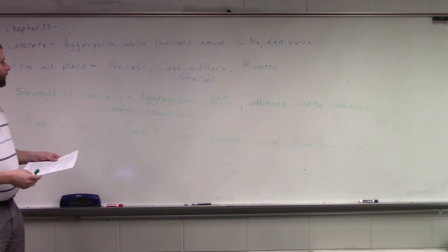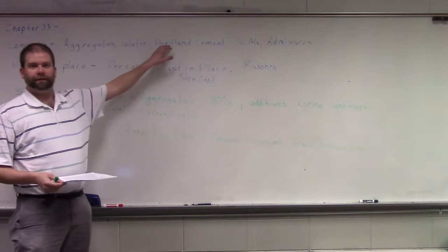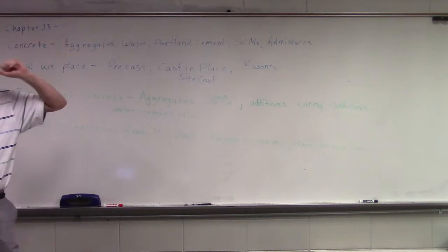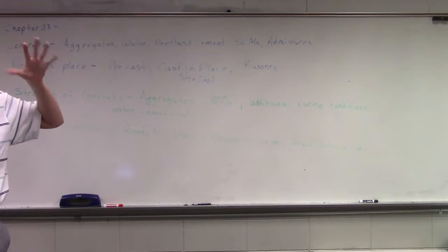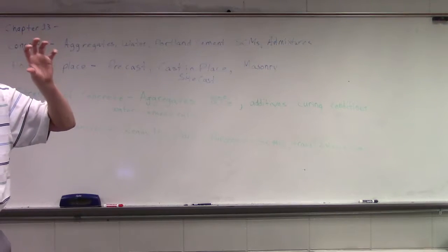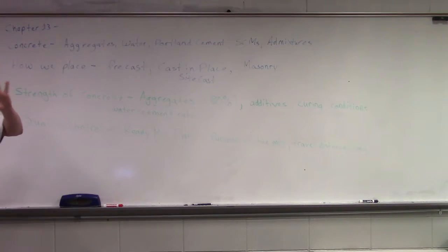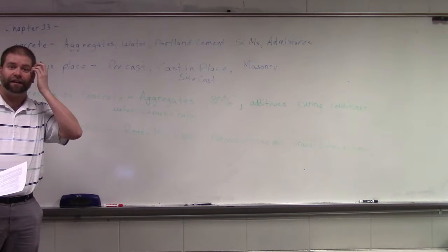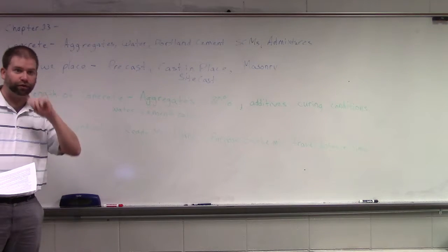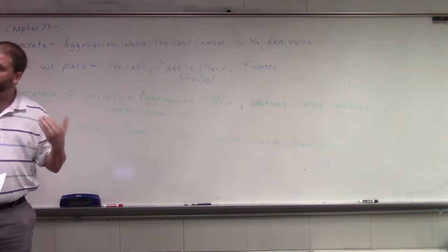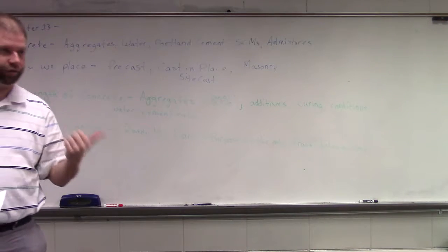When they talk about this Portland cement, we do truly have 5 types that are available to us. The only types that they really mention are general use, which is probably what you'll see on 90 to 95% of the projects that you work on in the Twin Cities area, okay? But we also have other products. We have sulfate resistance.